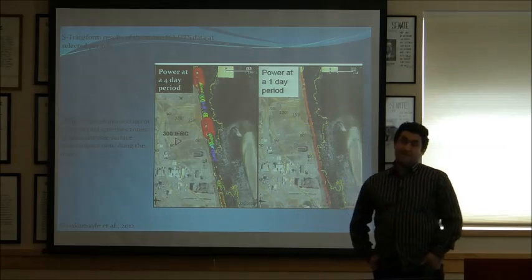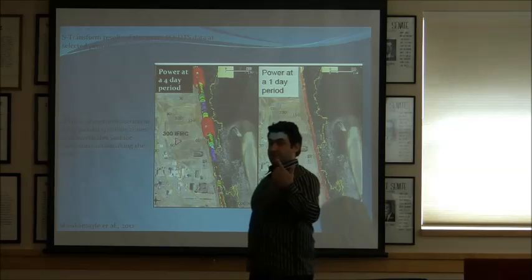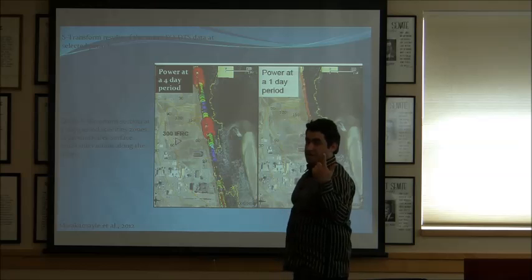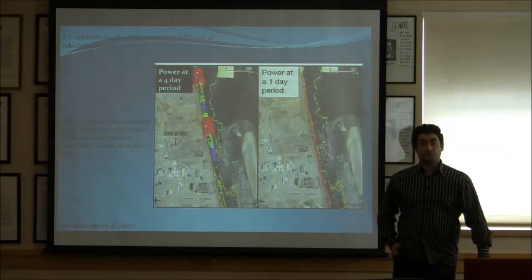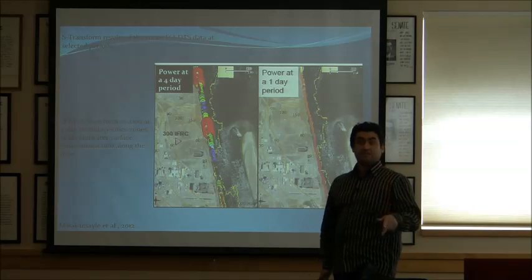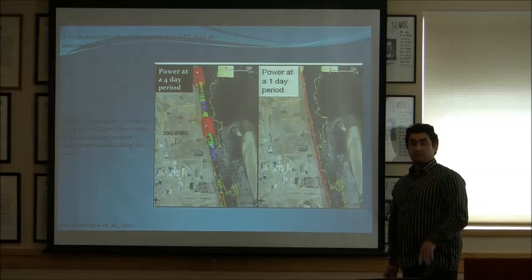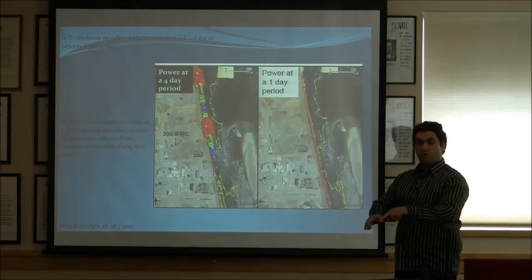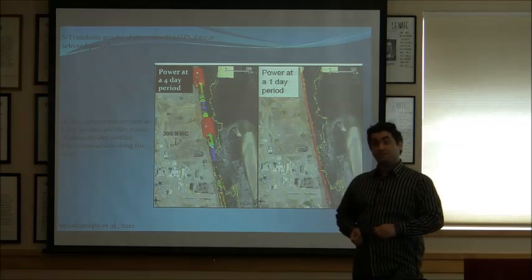And if you're looking for it, it's problematic, but usually we get rid of that by using a special type of electrodes called non-polarized electrodes to reduce the contact resistance between the electrode and the ground. This is one option. Another, if we don't have those types of electrodes, is we can just dig a hole and add water and salt, and we can do it.